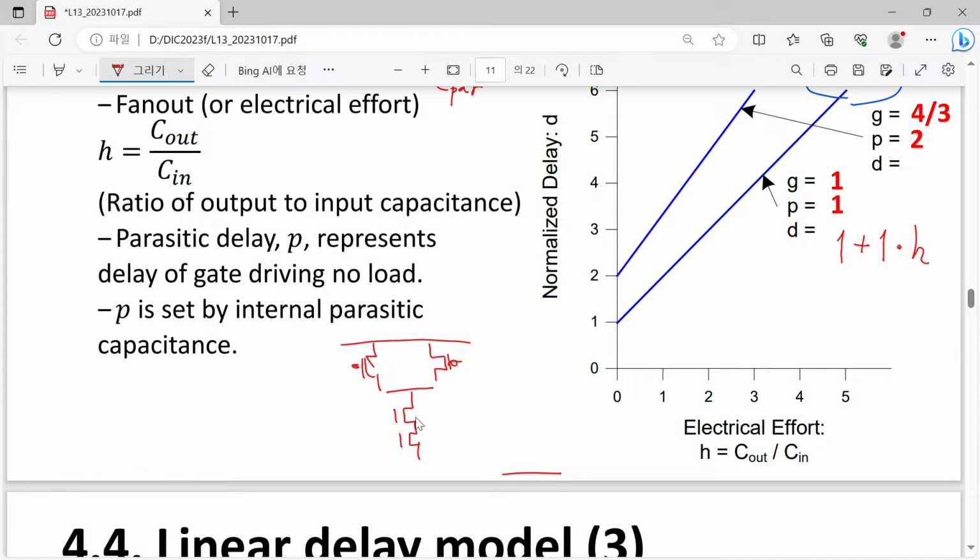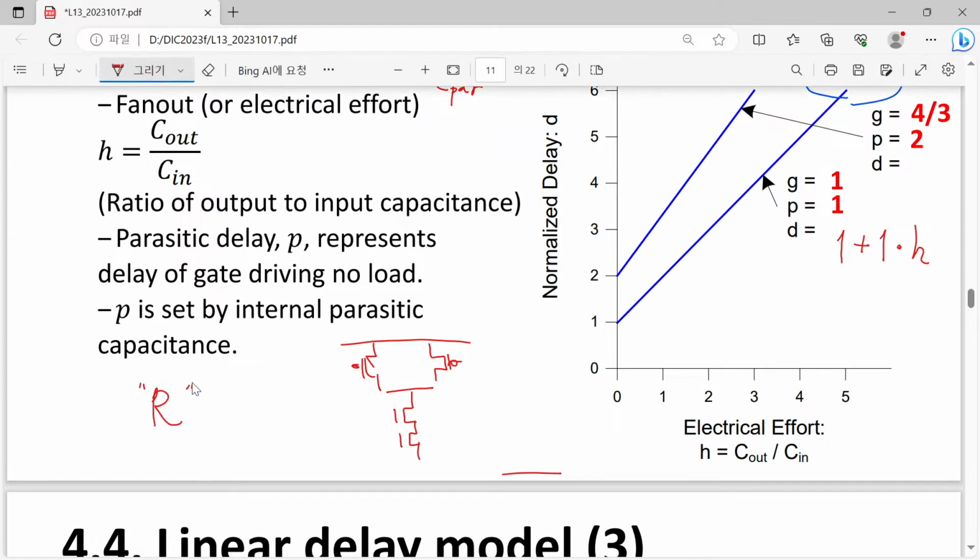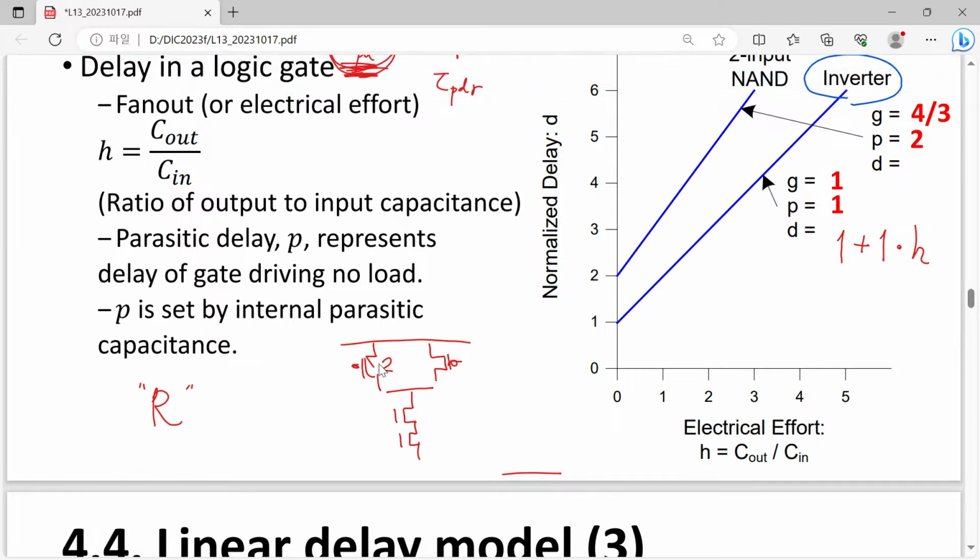Now in this two input NAND, how does it look? It has a P MOSFET, and another P MOSFET, and here we have a bubble, and N MOSFET, N MOSFET. What will be the size of a P MOSFET to match our DC purpose? In order to match the effective resistance of R, we have to have 2 as the width of our P MOSFET, because we are assuming that a P MOSFET is twice less powerful than an N MOSFET, so we must have 2.